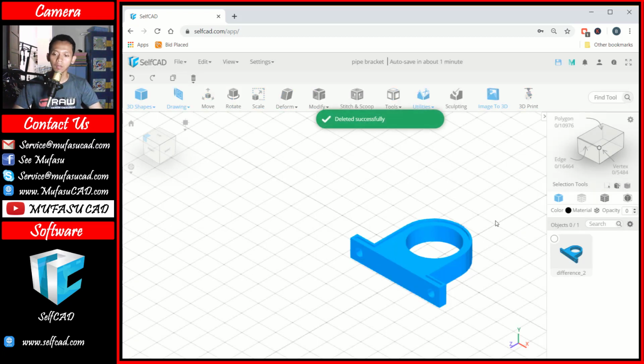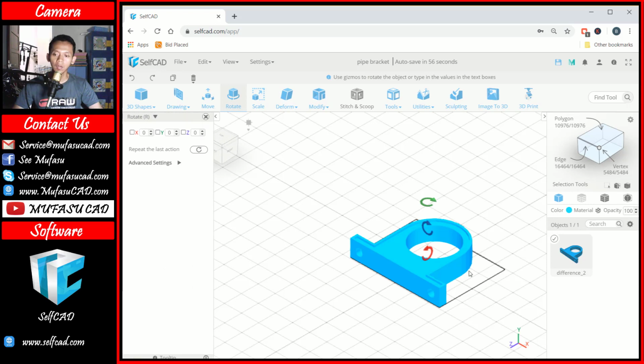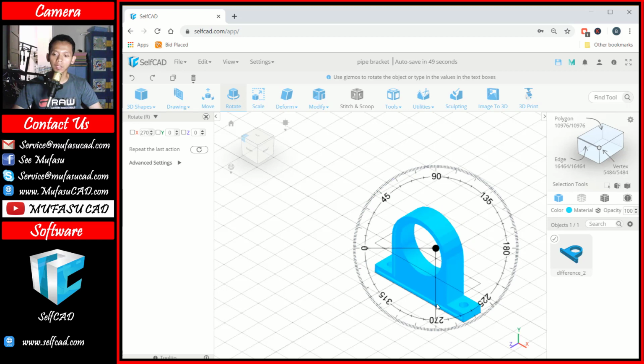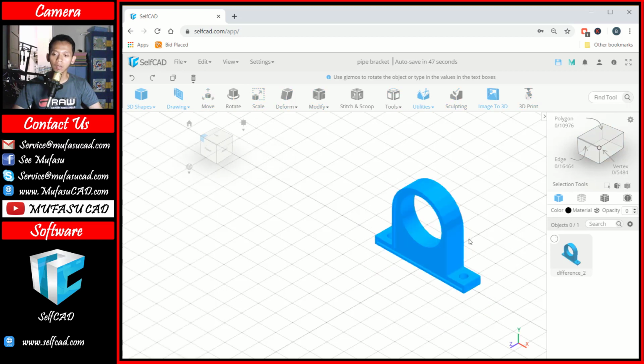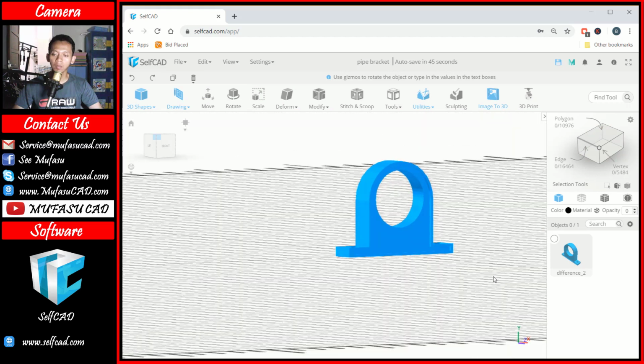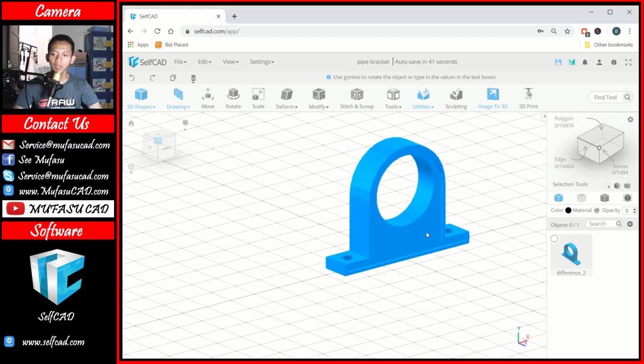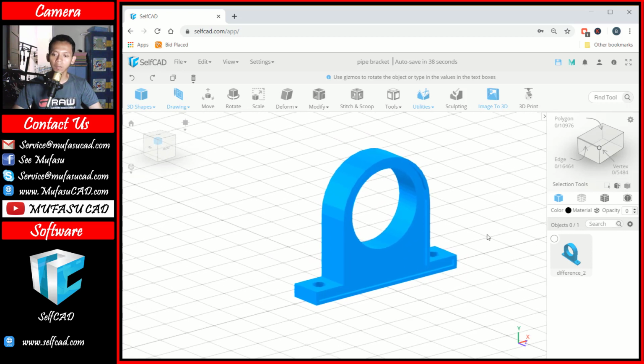Okay. Now I will rotate this object. Okay, you can click rotate. I will rotate in the right axis with angle 270 degrees. And now we already create this simple 3D model, the 12mm pipe mounting bracket, with SelfCAD software.